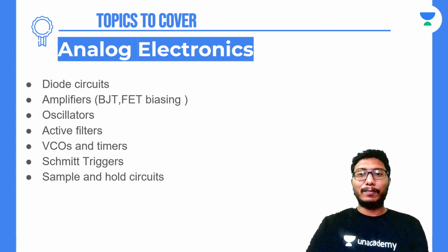So what we have seen is most important topics from BJT, and important areas where you can expect questions from BJT and FET are biasing techniques. You have to see the operating points where the FET is operating, and when it comes to BJT, it's about if the BJT is under saturation or cutoff or active mode. And after that, BJT has three different types of configurations for being used as amplifier, that is common emitter, common collector and common base.